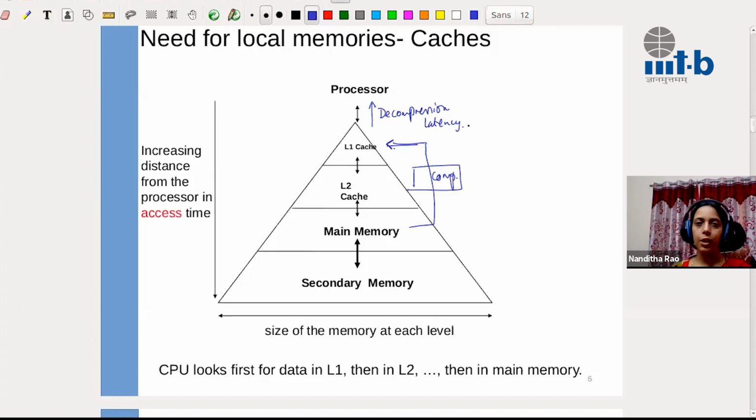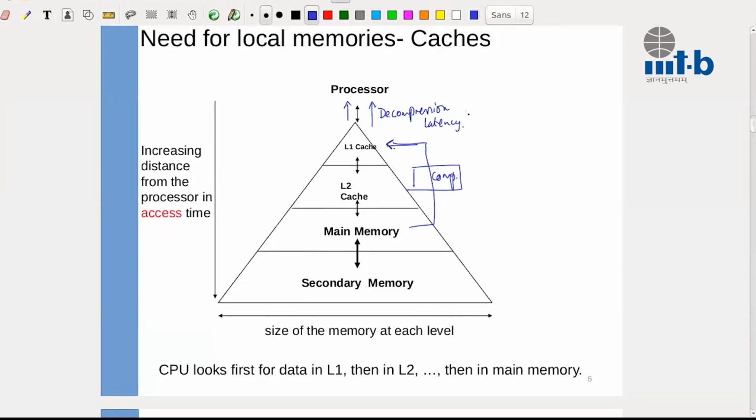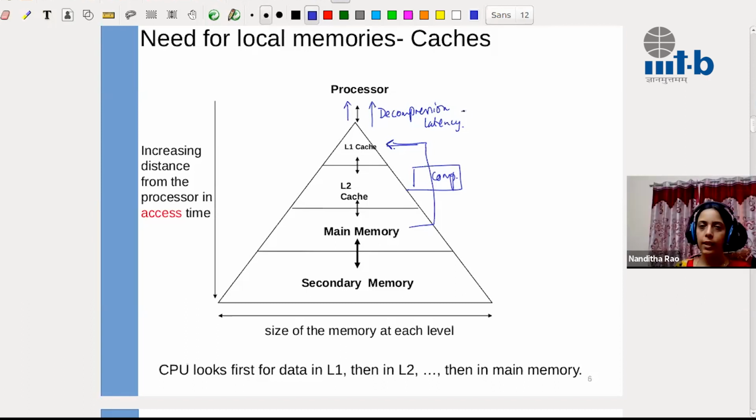So that is where our design space exploration comes into the picture. The compression latency is still fine because it does not really come in the critical path, whereas the decompression path is more critical because you don't want the processor to keep waiting for the data. So this is where the compression schemes come into the picture. You want to design a compression scheme such that the decompression latency is as low as possible. If not, you're going to have some performance impact due to this compression.